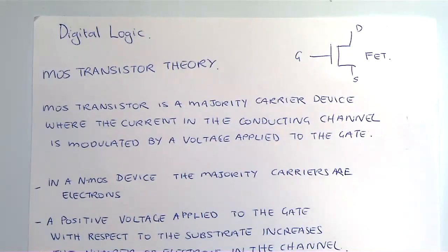On an NMOS device, essentially what happens is you apply a voltage to the gate, and if you exceed a certain voltage, that increases the electrons in that gate, which actually makes the device able to conduct current between its source and drain. Okay. And the higher you increase the voltage past its threshold voltage, and we'll talk about threshold voltage in a little while, the higher the current.